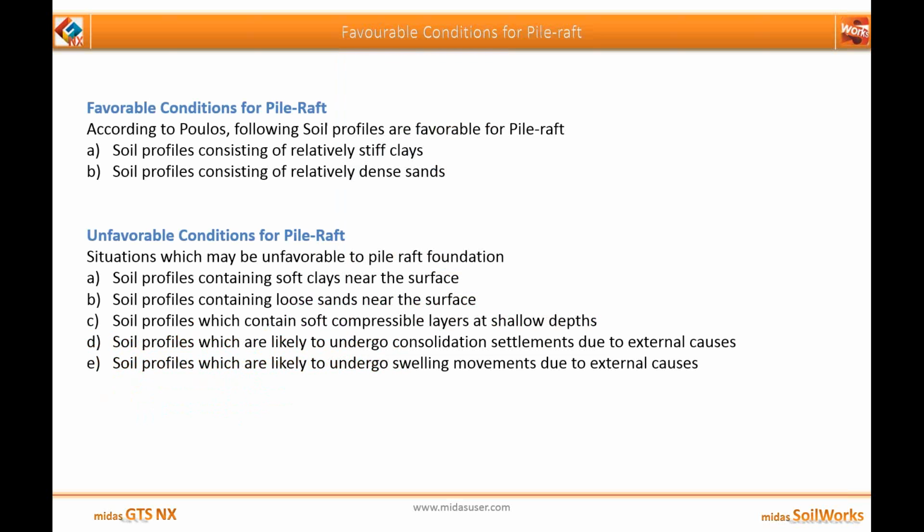Now, what are the favorable conditions for pile-raft? According to Poulos, wherever the soil profiles consist of relatively stiff clays or relatively dense sand, it is a very favorable condition for pile-raft. Why so? Because the raft has a very high bearing capacity in that case and provides proper stiffness to the foundation. So the piles just act as a support which enhances the overall function of the pile-raft foundation.